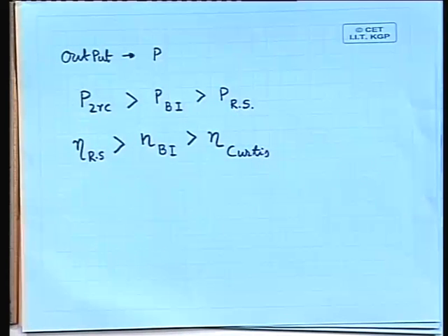Okay. So, you see that these two pieces of information are opposite to each other. That is why in a steam turbine design, particularly if it is a large steam turbine, we should have a combination of all three stages to get the maximum benefit out of the supplied steam. Okay. And it is like this.